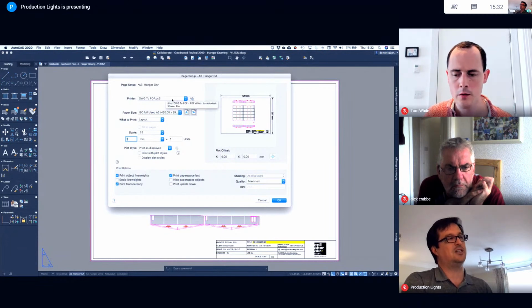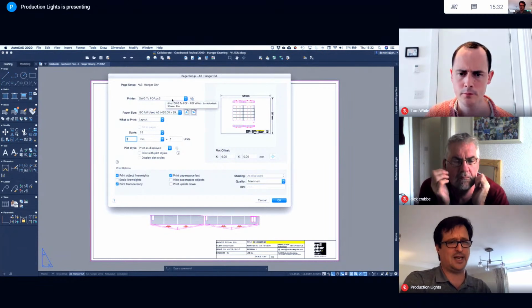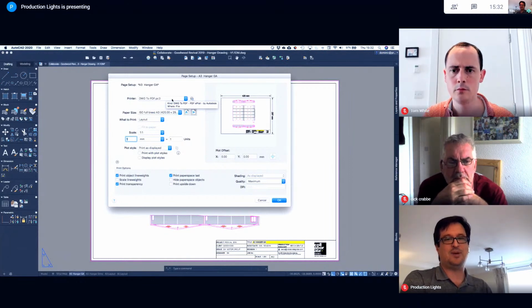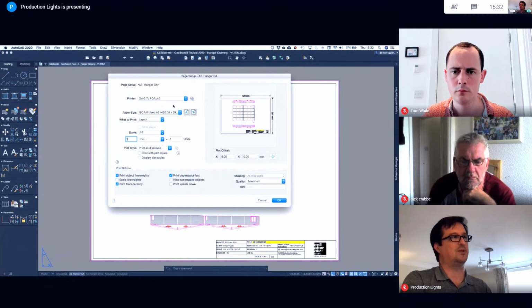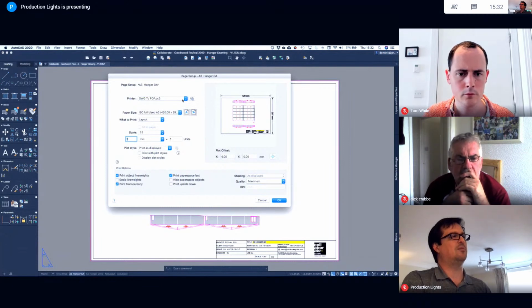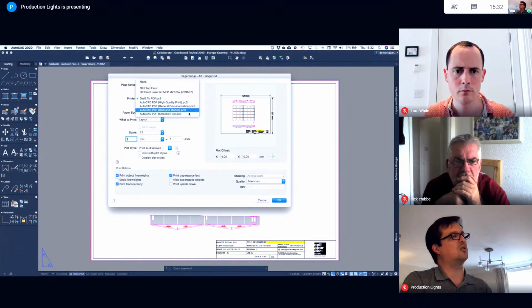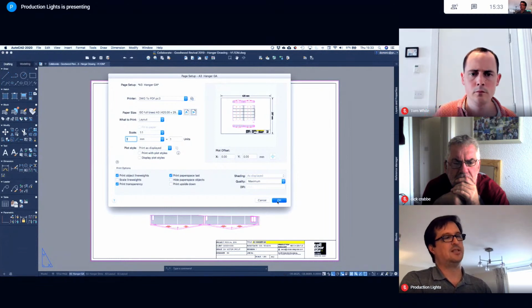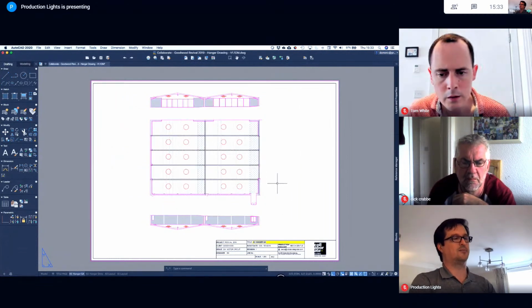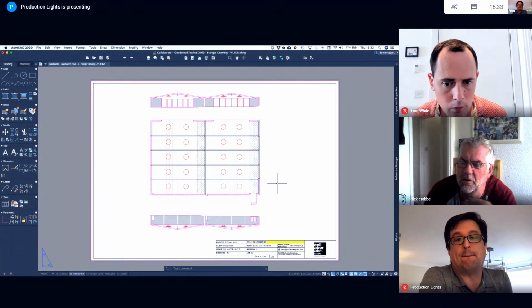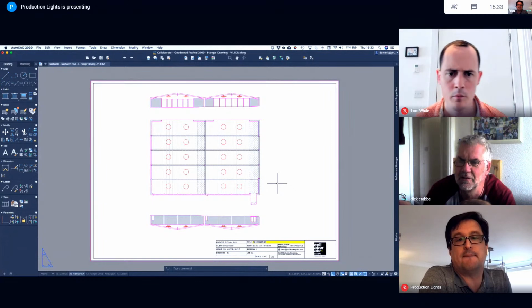So here, very much like Tom, it's DWG to PDF 3, and I think you're correct, it's been here for 3 years. And it's much better than having a non-AutoCAD PDF publisher. QPDF was great, but it did have its problems. So you get it here, so to PDF. Can't remember, it does different qualities as well. You can choose different qualities, but straight PDF is fine. Paper size, scales, as Tom talked about. So having that set up correctly is really, really good. So all that's set up as part of your template.